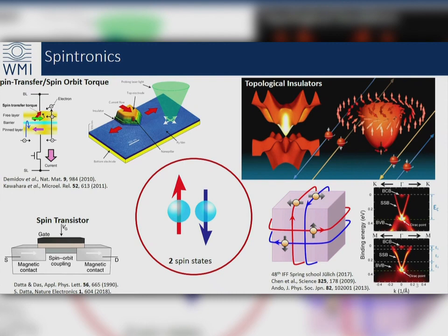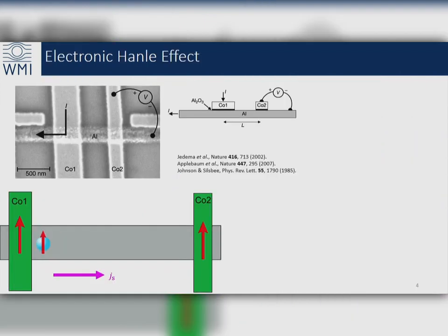On the other hand, this is one of the proposals, the spin transistor, that has been around for quite a while, proposed by Datta and Das, where the idea was that in this channel, when you inject spins, you rotate them by a gate-controllable spin-orbit coupling such that they can rotate and you can really reverse the orientation. And of course, currently all of the experiments that have been done in this direction show that there is some way of manipulating spin-orbit coupling, but the effect is so weak that it will not work for device applications. Still, this rotation that you can do with the spin is useful in the experiments, especially if you want to prove that the effect that you measured is coming from the electron spin and not some artificial effect due to your structure here.